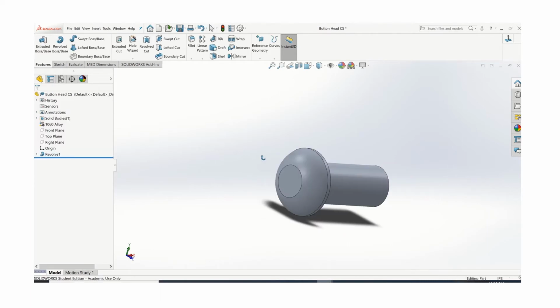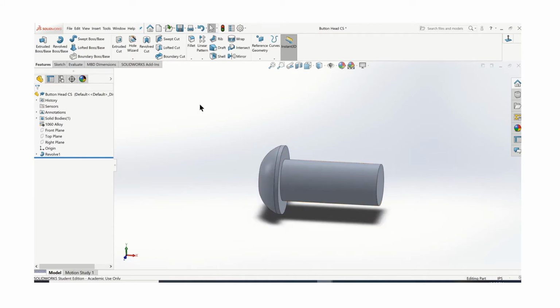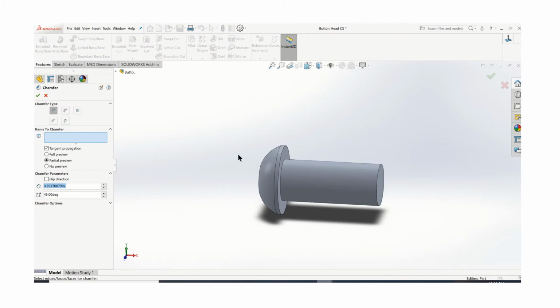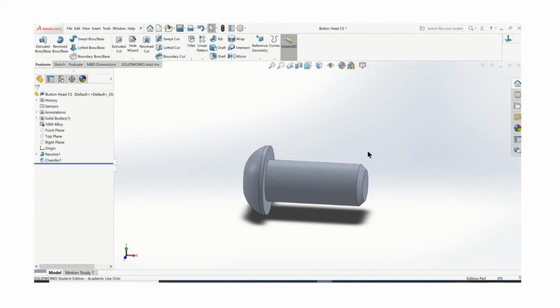To create the blank for this, we need to put a thread on it. Now before you put a thread on, you're going to want to put a chamfer on that. So use the chamfer tool, and that chamfer is 20 thousandths, so it's going to be .020. Standard is a 45-degree angle, so all you've got to do is click on that corner right there to put the chamfer on it. You always want a chamfer on a threaded fastener. It just makes it so much easier for it to function. To put the thread on there, go up to Hole Wizard and just click on Thread.